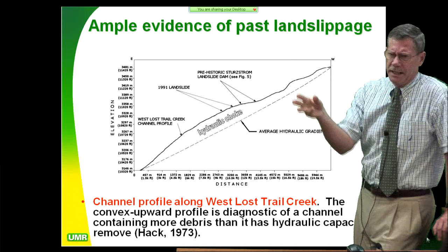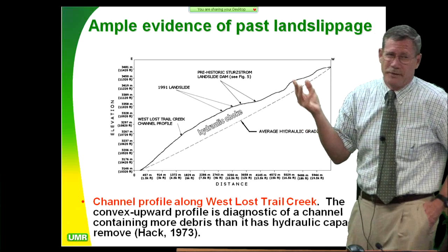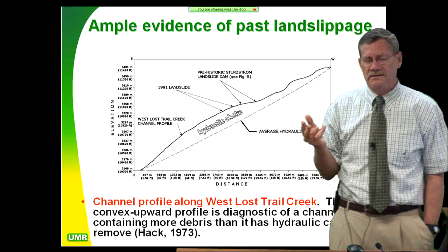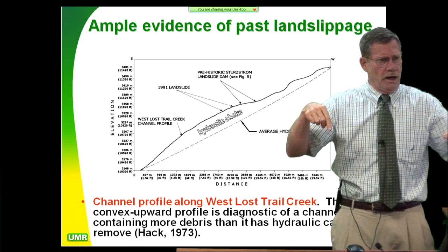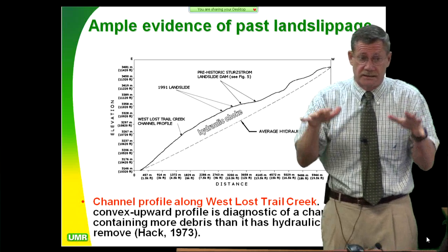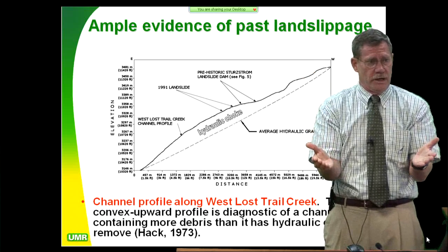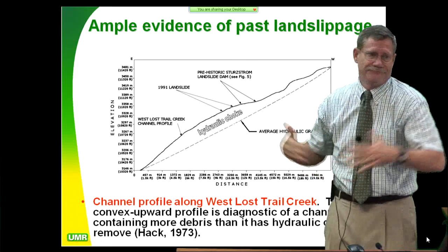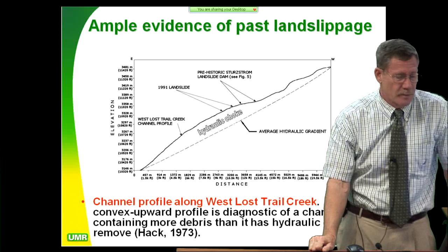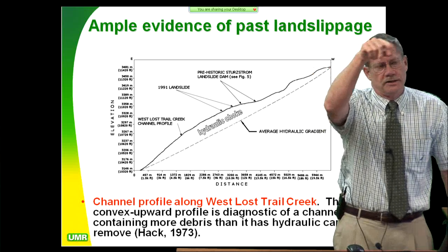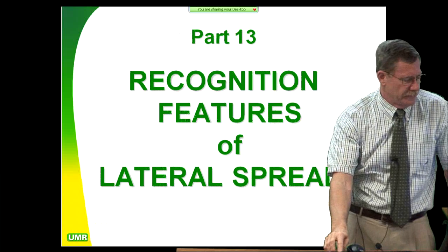A huge flood. We had Madison Canyon occur in 1959, also triggered by a magnitude 7.4 earthquake, 7.7. That one is a much smaller watershed, so the slide block's still there. The Corps of Engineers came in and lowered the channel about 40 feet to provide a natural spillway, and it stabilized itself. It's been that way for the last 50 years. But Gros Ventre had a much larger watershed, about 1,600 square miles, so it got blown out pretty rapidly.